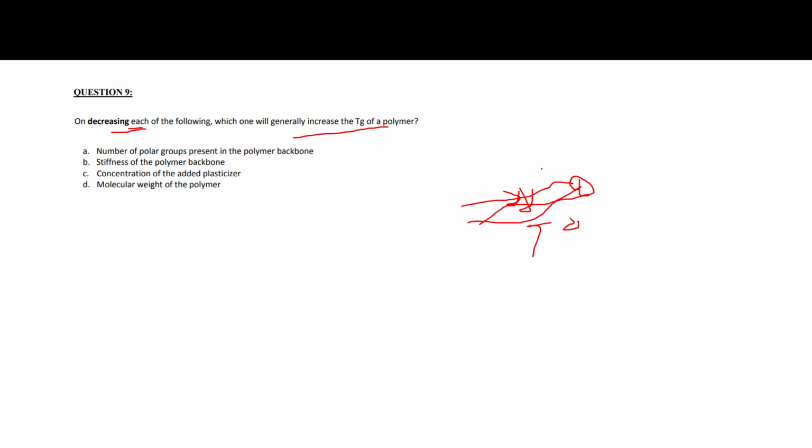So depending upon the material we are going to use in the polymers, the polymer properties are different. If you use some additives which harden the polymers, so that they become hard materials, the Tg of the polymers will be increasing.